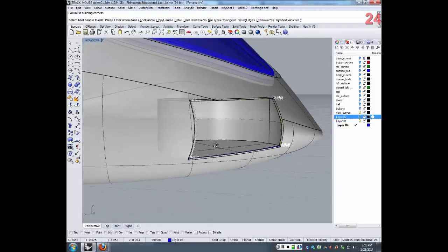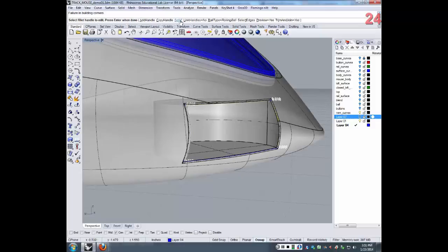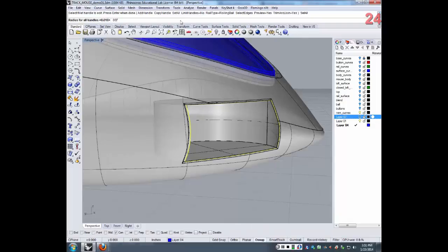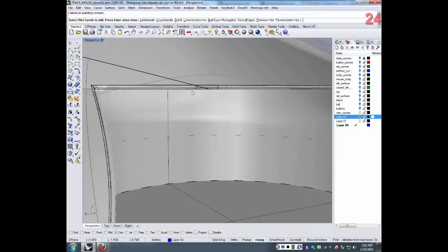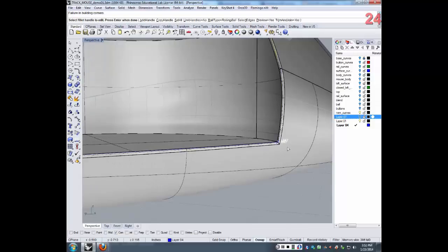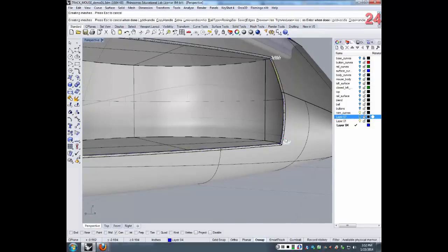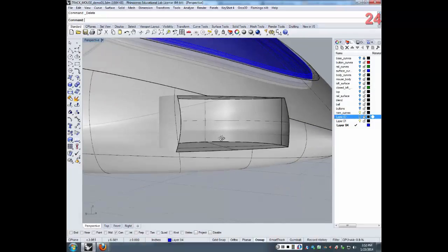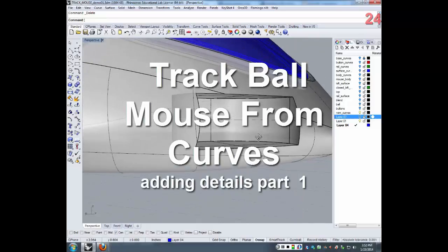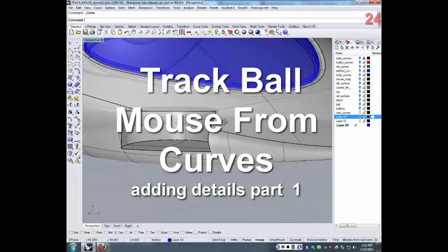And let's set all to 0.007. And that looks clean. Okay, so that's going to be a tiny, tiny wee little fillet. Okay, and did it work? Nope. So that tells me that there's a problem with these curves. Huh? There's a problem with these curves. Now let me show you. I'm going to show you a little trick. This is some power modeling here, to fix a problem like this.